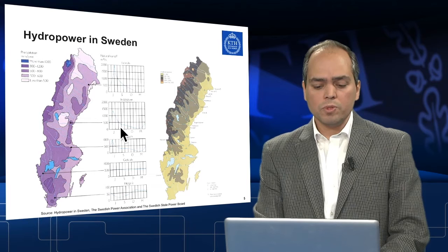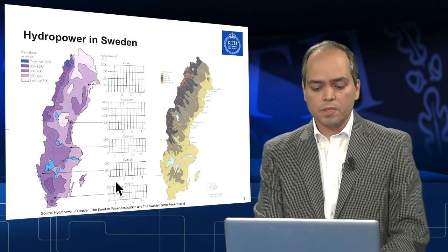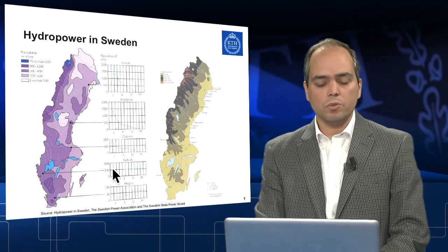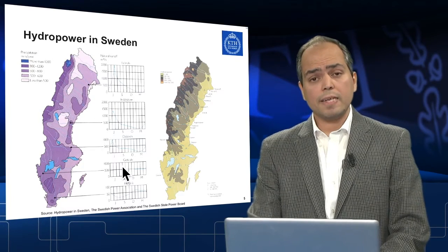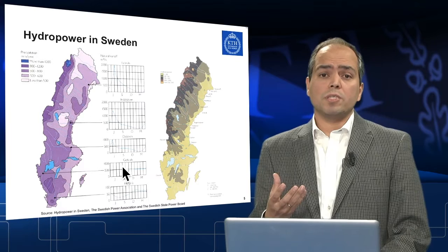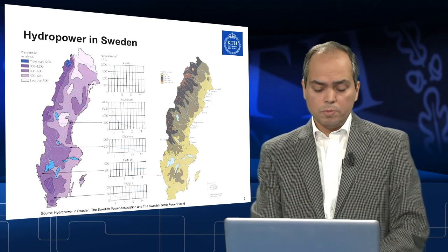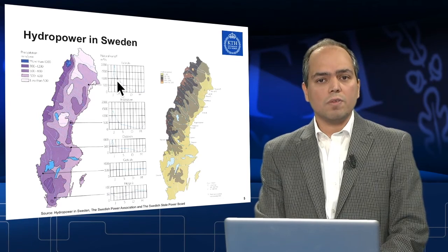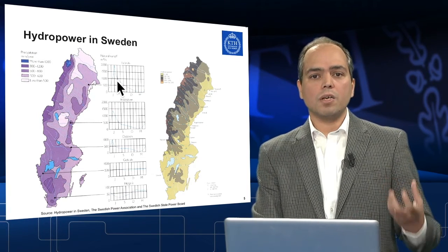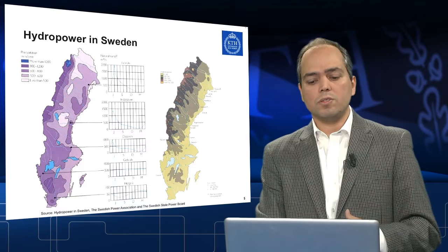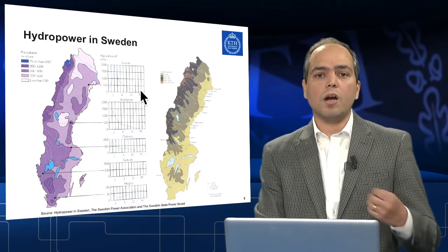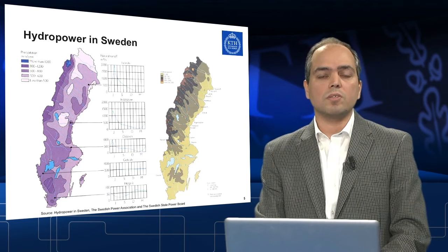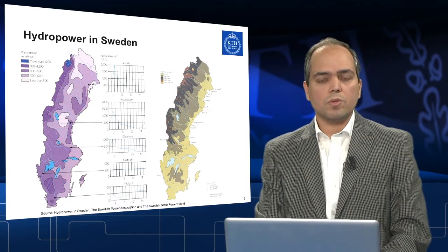And when we move to the southern parts, because of the weather effect, the runoff becomes more uniform all along the year. And this is one of the main aspects of large-scale hydropower. They could be used in order to even out the runoff and store it to be used in other periods of the year. So the large-scale hydropower plant could be used as some sort of energy storage.